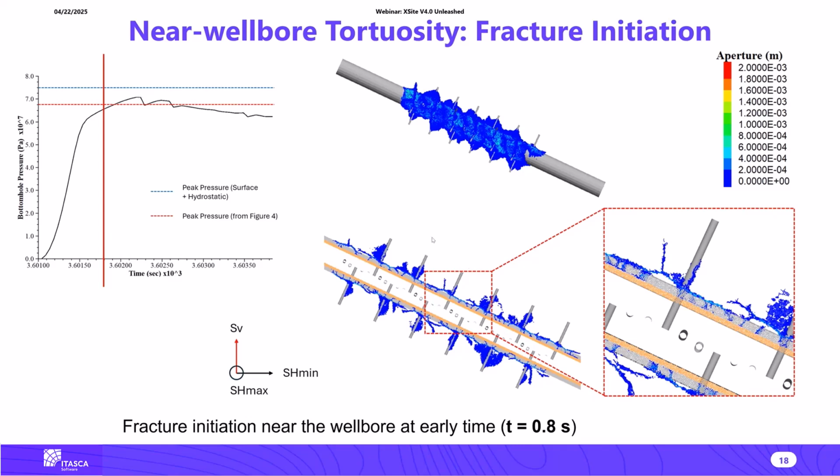On the right, we show a side view showing the well and perforations and induced micro cracks. But then we also show the model in the vertical cross section with zoom in detail. If you look at this, you can see interestingly that the fractures initiate from perforation, but we also see that the finite strength of the cement has a significant effect. So the cracks also propagate through the cement and also in the interface between the cement and the rock.